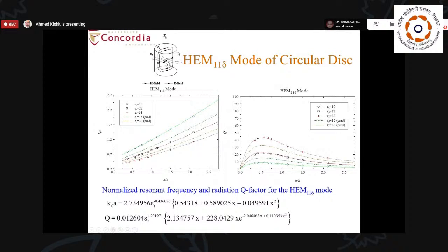And the one here means the phi variation is like a sine phi or cosine phi variation. And once you introduce variation in phi, TE and TM will never satisfy the boundary conditions for this dielectric resonator, and that's why it has to be a combination of TE and TM. For this mode, it has a certain field distribution that we must be familiar with in order to know how to excite it, as we will see.